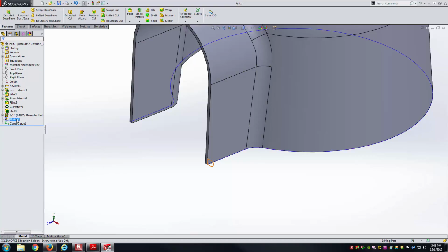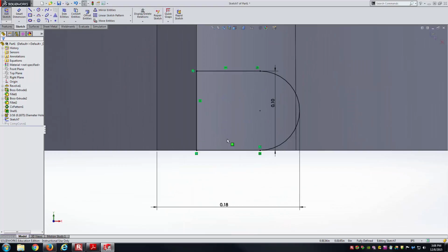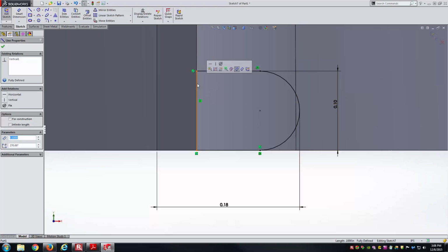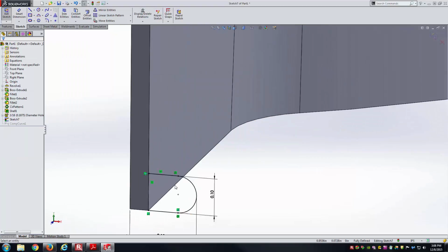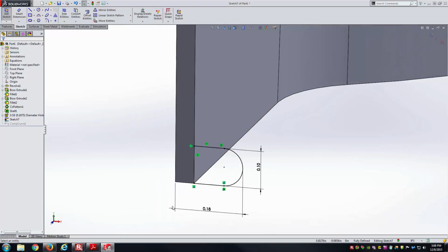My solution is going to be to adjust the profile. Here I'm going to get right back into sketch 7, which is the profile sketch, so I'll edit that sketch. I'll hit Control 8, and now I'm normal to the sketch, so this is back to where we were. What I'm going to do is make sure that there's some intersection between this area that I'm trying to use for my profile and the actual geometry here. So I'll select it and go construction geometry. I've kept that line that I had as a boundary, but now I'm making it construction geometry.